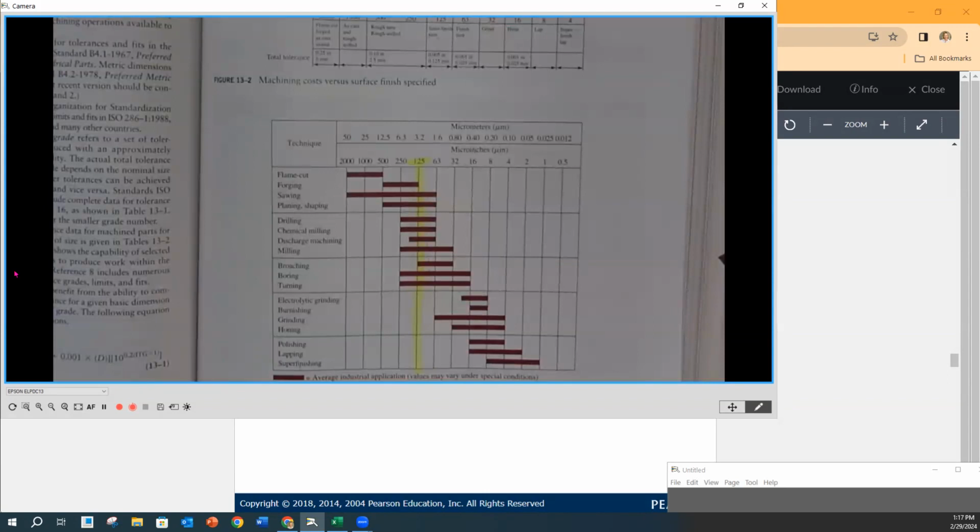What you would want to avoid is putting it way down at like an 8 surface finish, because then you're going to have to grind those parts, and that's probably overkill for your application. Okay, because in this instance, we had a mandrel for a different line, different snap ring and whatnot, and I just copied their finishing, and they went to a 16, so that's what I did. Yeah, so that's on the far end of turning. You might even get into some grinding or something to finish that.